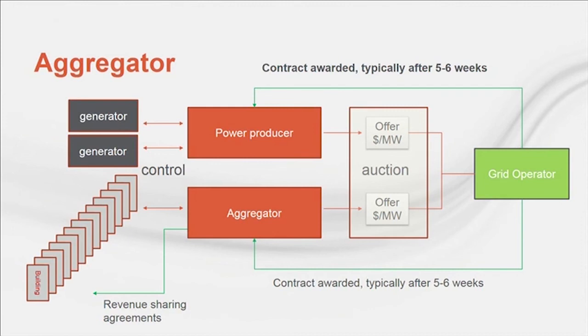Aggregators receive payments throughout the year based off of the availability of the demand response resources, whether an event is called or not. It is more often than not that an event is not called within a season, and the aggregator will receive payment for having load on standby. If an event is called or an annual test is issued, the aggregator will be responsible for ensuring the end user effectively sheds the load within the time allotted, typically 10, 30, or 60 minutes.